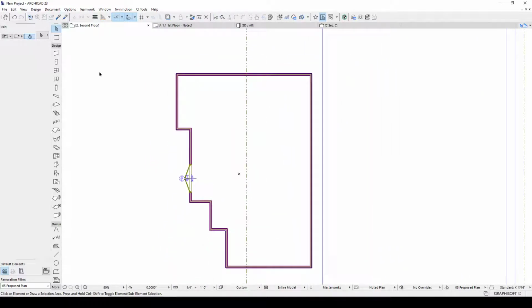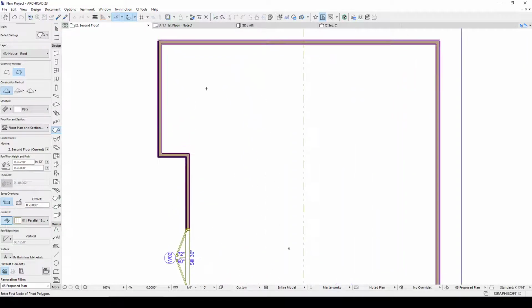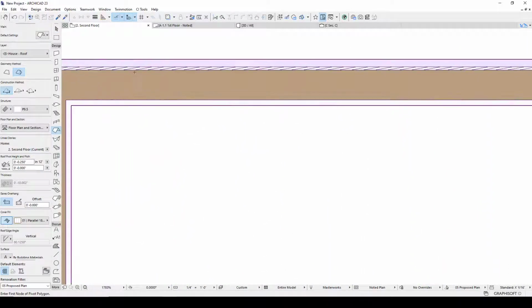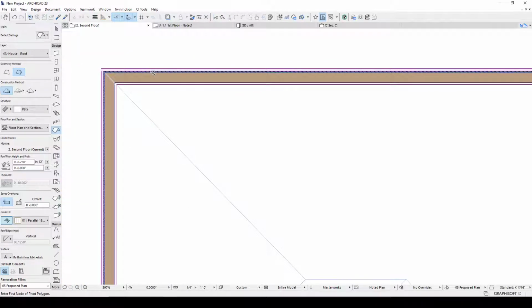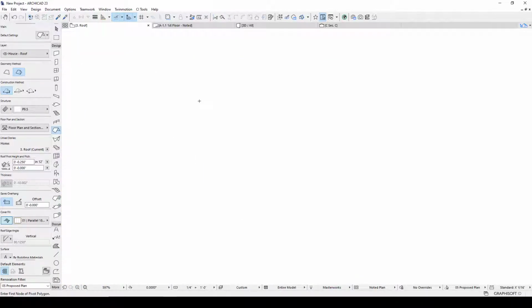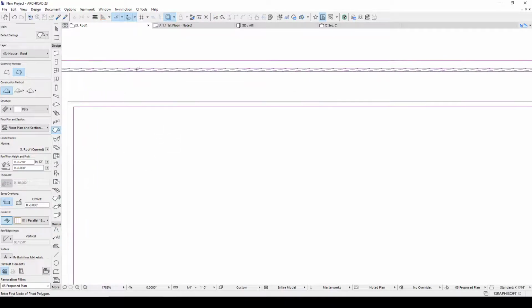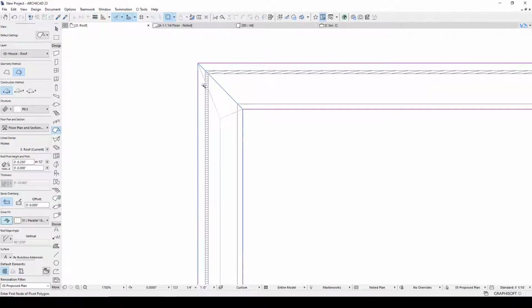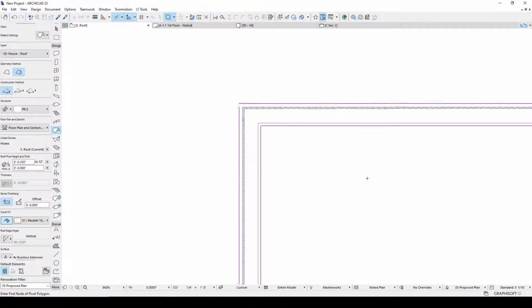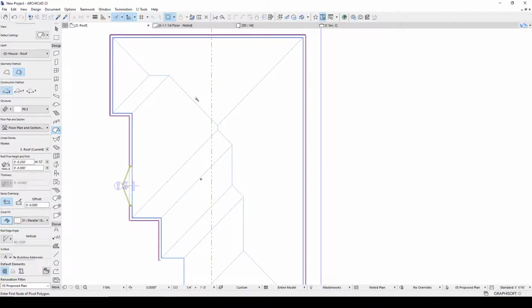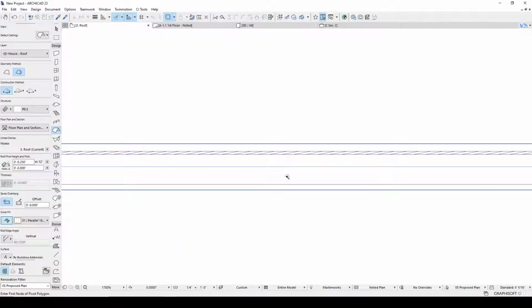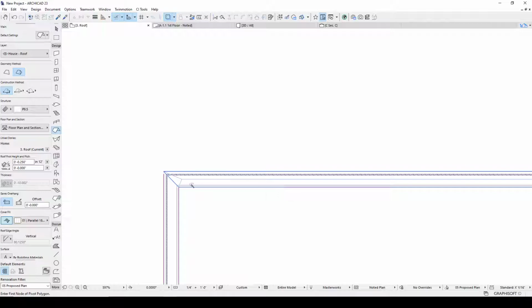And what I found is it's easier actually in some cases, not all cases, when I want to do a magic wand, I'm not able to do that through a trace. So let me show you. Here, I'm on the roof story. If I trace, when I try to do a magic wand, well, I guess I could do it here. That actually does work. I can magic wand inside the building. Normally what I do is I want to magic wand one of these wall sections, but it's trying to trace the actual wall element itself, which is not very helpful.